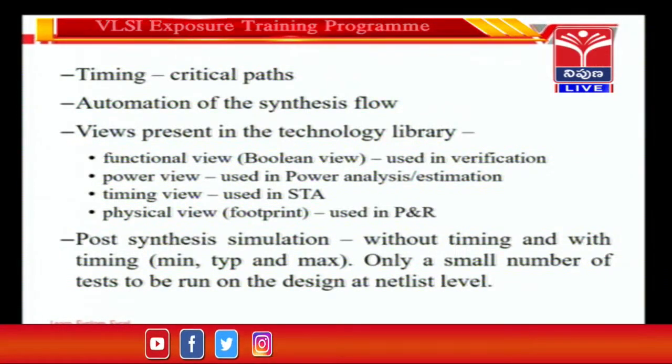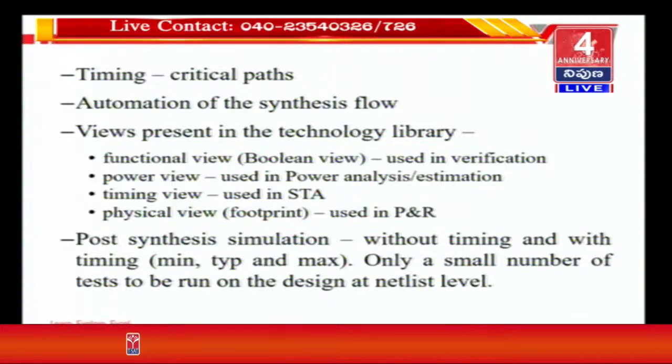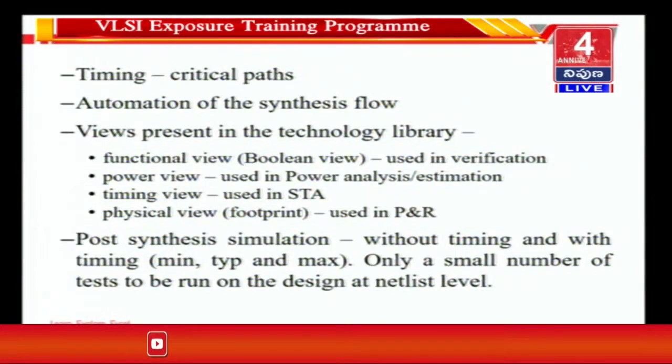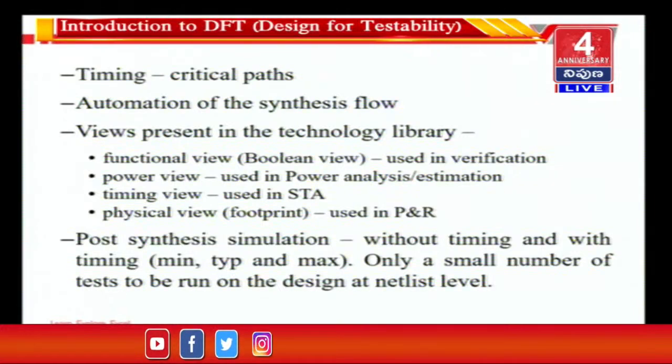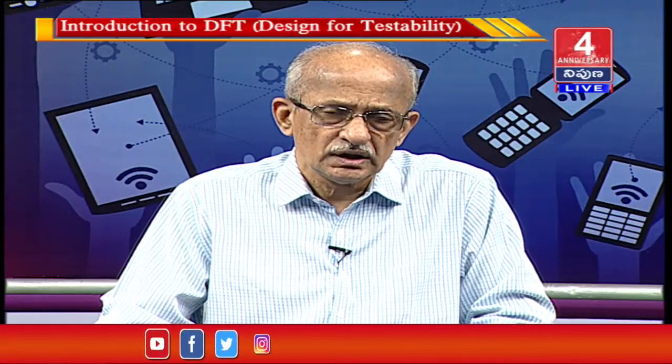Therefore it takes the timing information from these logic libraries, and if at that stage interconnect delay information is also available, it will take that also and come to a conclusion as to whether certain paths are critical, some paths are violating the timing requirements, or all the paths are meeting the timing requirements. If they are meeting them, by how much margin? All this information will be available when the static timing analysis tool runs on this particular netlist. This is only for timing information, which can be obtained through the use of an STA tool, a static timing analysis tool.